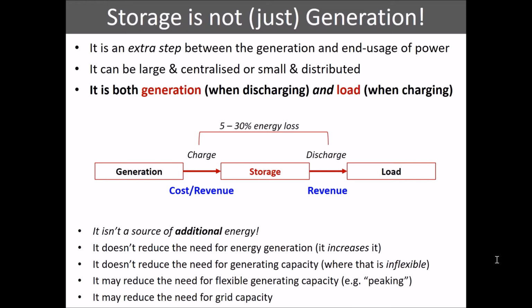You can also have it as a source of load that you can turn up if need be or turn down if need be. So in that sense, that places storage in a rather unique market segment compared to, for example, a diesel generator or a gas peaking power plant, because it has some extra advantages. Depending on the technology, it can be very, very quick to react, but also it can react in both directions. It can provide more power, but also it can suck power out. It can increase the amount of demand if that's a desirable thing to do, for example, when you've got too much wind.